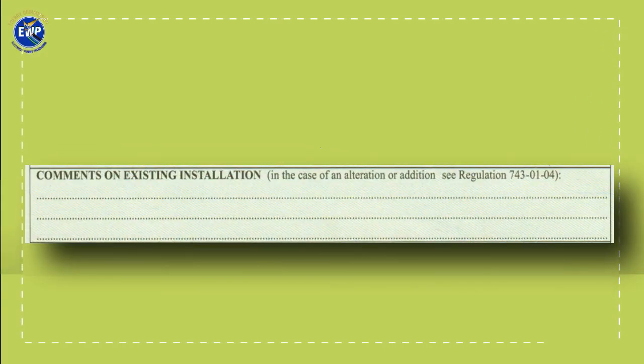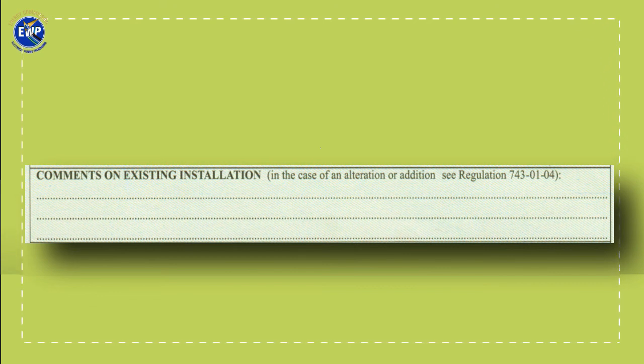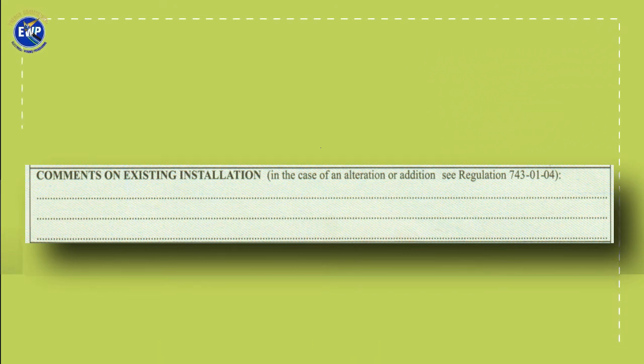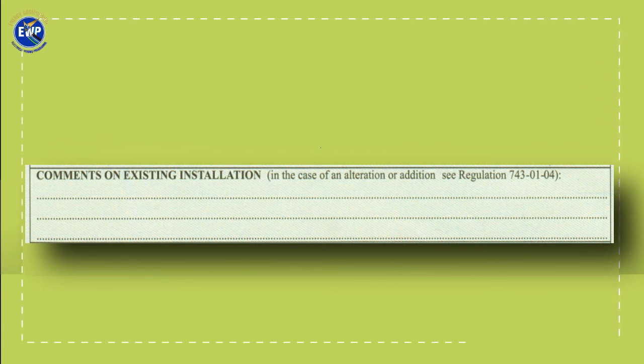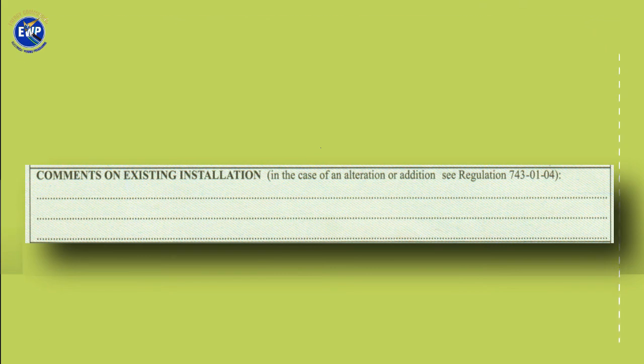Next is comment on existing installation. Now, having gone through all the inspection and testing procedures, if you find that there is a need for you to make a comment, you write whatever comment there is. Sometimes you find that during inspection, the installation violates some aspects of the regulation. It is important that you state that here. Or, in order not to leave the place blank, when the inspector is satisfied with all the inspection and test process, there is nothing wrong, maybe write here, satisfactory.